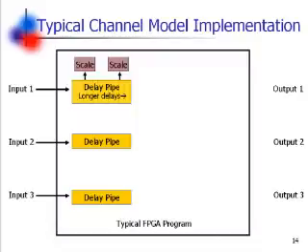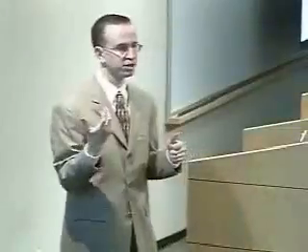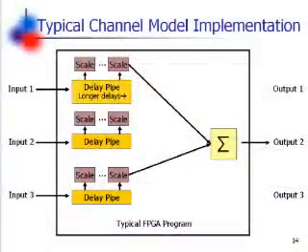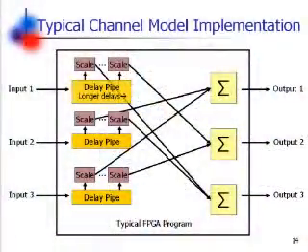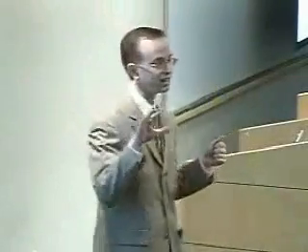Then at a specified delay, we can pull off a copy of the signal and scale it by whatever factor we want. We do this for every single source. And then for each receiver, we decide which delay it wants to hear from each source, and we just sum them up and send them out to the receiver. So it's a fairly simple circuit. We do that for every single source and receiver set. And then the real trick really is the modeling. That is changing those scaling factors and picking the delays appropriately in order to model our environment.